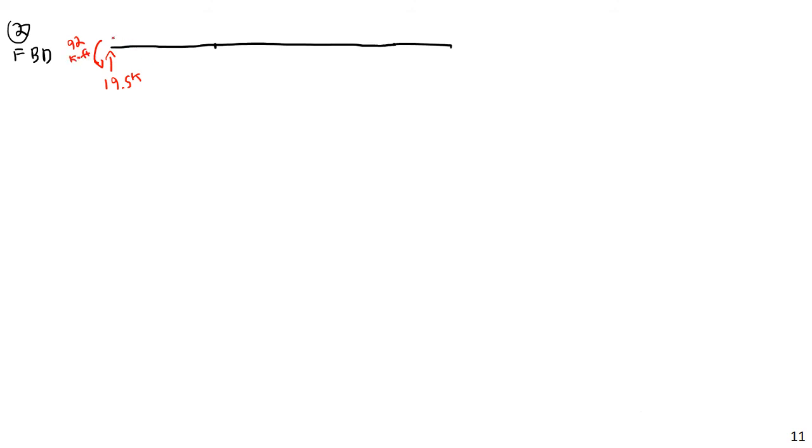And then I have a distributed load of my 2 kip per foot load, all the way to the hinge. Two kips per foot. Then I have a 10 kip force here. Again, this is actually an applied force, but when you do the global free body diagram like this, the final free body diagram, the distinction between reactions and external loads is lost. Or not just necessarily lost, but it's irrelevant.